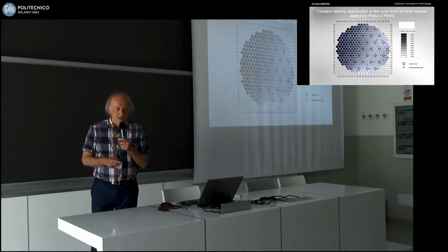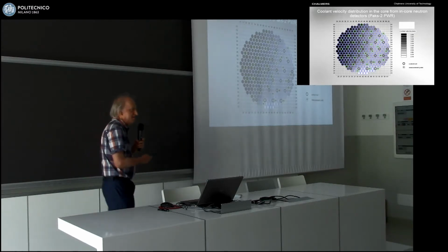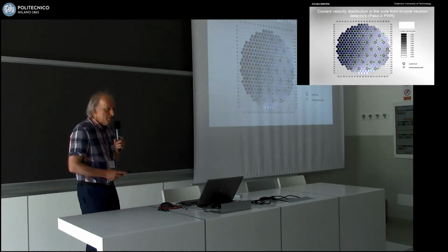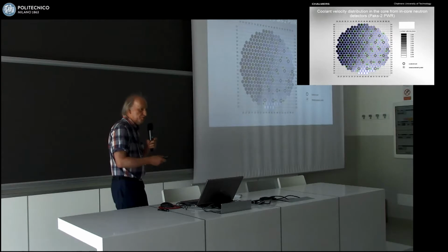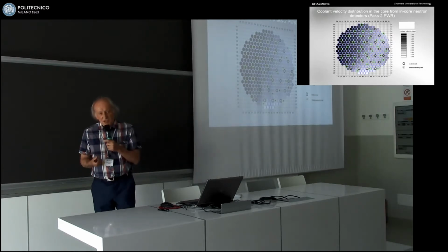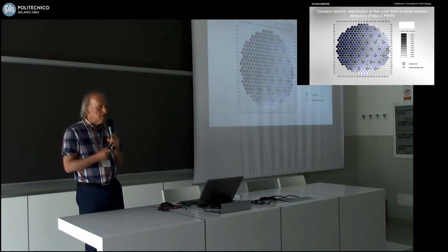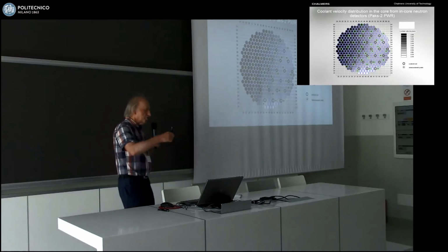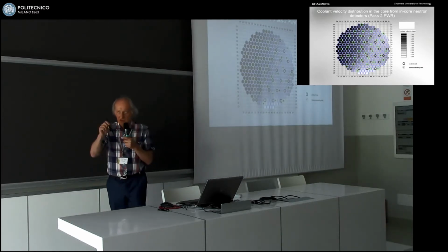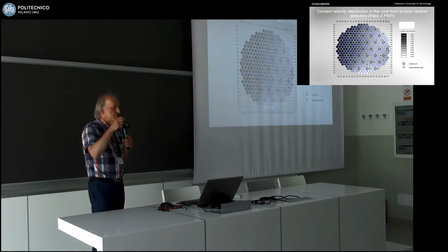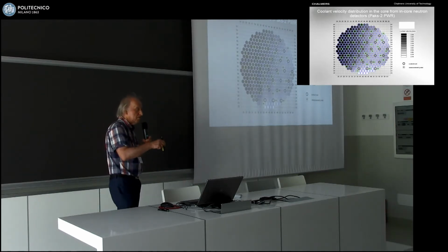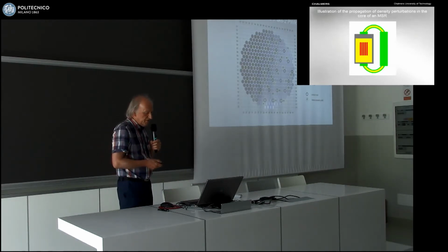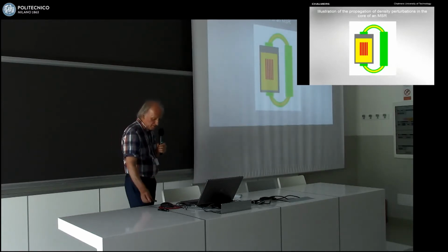Of course, in a way you can say that this is too early. We don't have any reactors. We have more important points. That's true, I agree. This is kind of marginal. But once you fix the design, it will not be possible to put any more detectors in it. So for instance, in the Swedish pressurized water reactors, we don't have one single standard in-core neutron detector. We have traversing in-core tips, or movable detectors, that's the name in the pressurized water reactor, which you can have at a maximum of 20 minutes in the reactor for different reasons. So it's very good to think of it, even if we don't know what type of perturbations can occur.